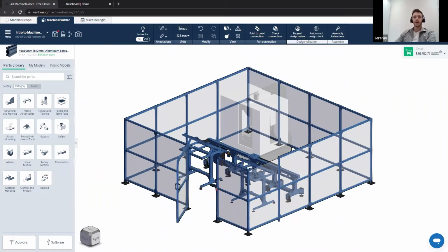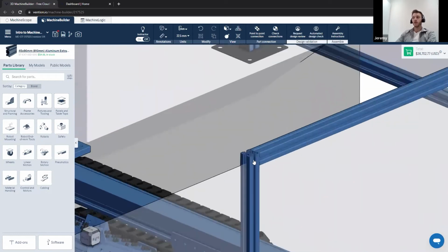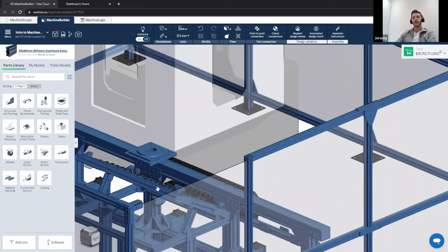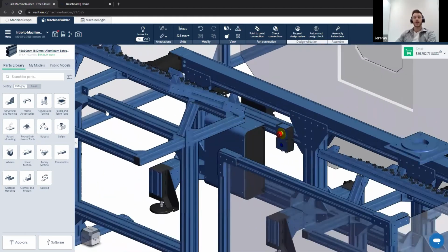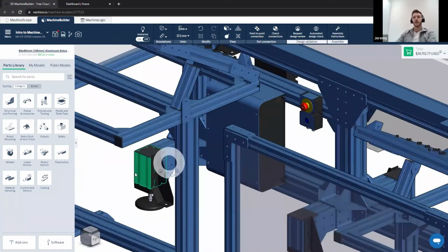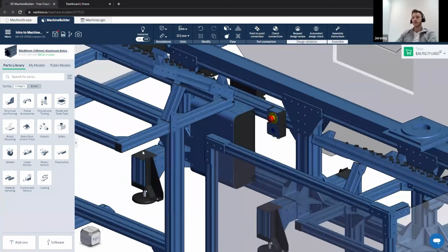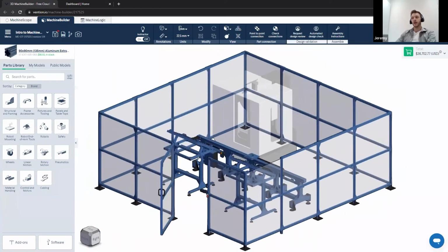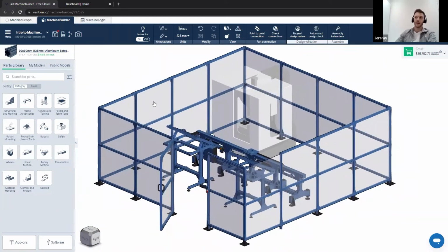Great. So from here, I'll jump ahead to the units measurement over here, which is one of the most used or highly important parts of the top toolbar. So Vention's ecosystem is designed around a 45mm increment or some fraction thereof. So if I zoom in a little bit over here, we have the extrusion profiles that are either a 45 by 45mm, zooming into the part presenter, a 45 by 90, and larger ones over here, a 90 by 90 profile.